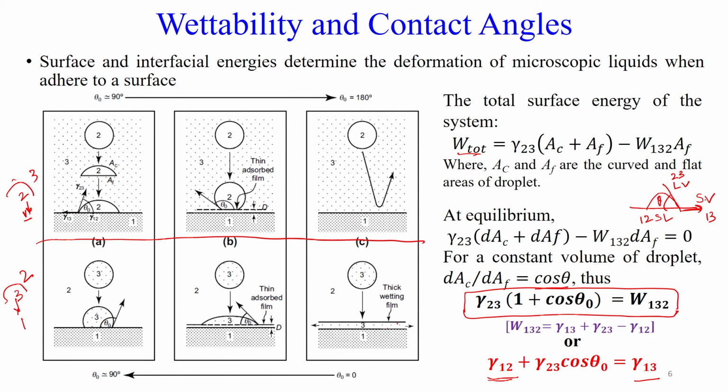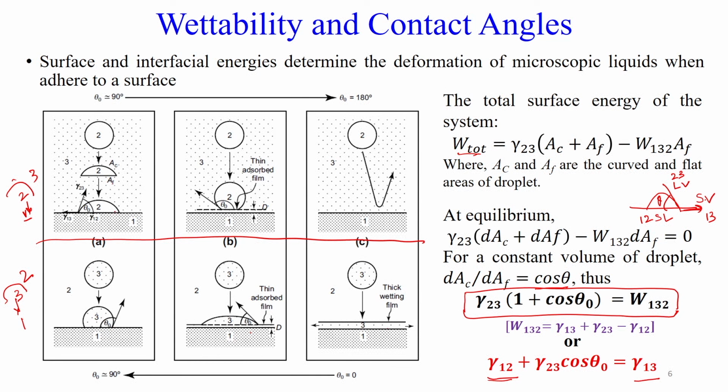in this case it is completely wettable. In this case this was hydrophobic, now it has become hydrophilic. In this case it was hydrophilic, now it has become hydrophobic. So, what it suggests is, although we are dealing with three systems, how they interact is going to affect the wettability or the contact angle. And it was a very interesting observation that when 1 and 2 are contacting in medium 3 and when 1 and 3 are contacting in medium 2, theta should be replaced by 180 minus theta.